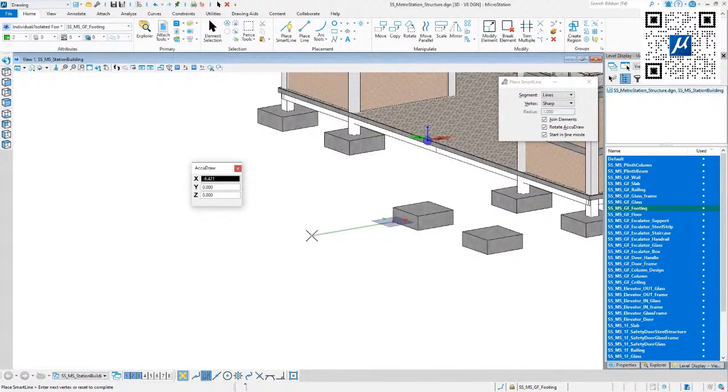So place the compass at the location you need, and then look at the mode, polar mode or rectangular mode, depending on what you get, and then you can rotate the AccuDraw compass to top, front, side maybe, or other options. And then you start drawing. And drawing with AccuDraw is so easy. You simply move your cursor maybe to the left, and then AccuDraw will notice, okay, he's going to the left, that's minus X. You can see minus X in the dialog.